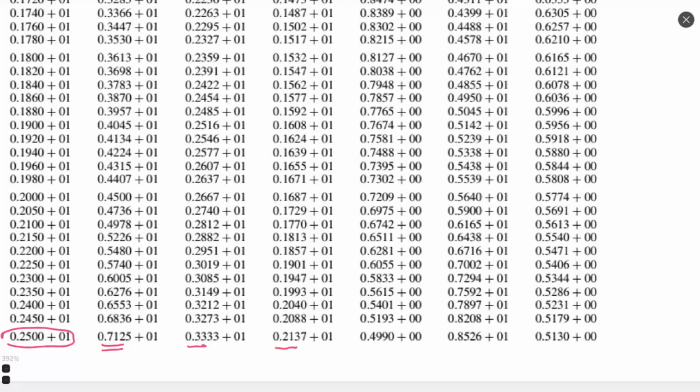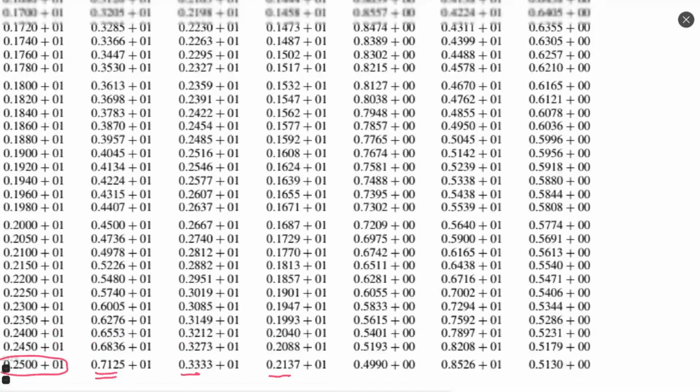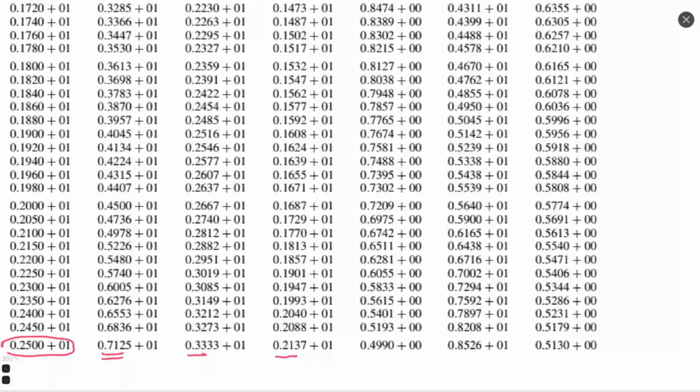It is one of the problems of mechanical design of structures that fly at high supersonic velocities. When we see the efficiency, the next column, we see that at Mach 2.5 we already lose 50% of energy just on the transition through the normal shock wave. It's a lot.